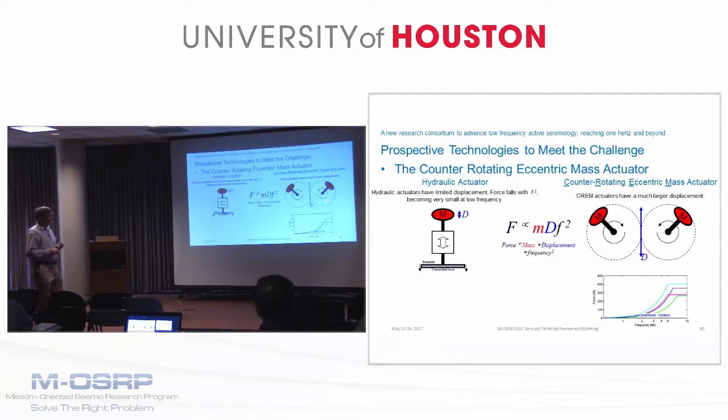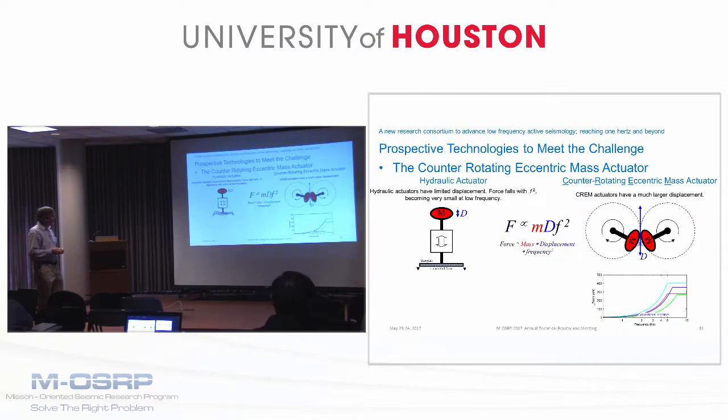And then I have a second one over here, which is rotating in the opposite way, and the idea is that that cancels out all the horizontal forcing and leaves just the vertical forcing. And so it looks something like that. You can see the star is meant to indicate the center of mass of the system, and you see that mass is going just straight up and down, vertical. And that's going to provide a force in the vertical.